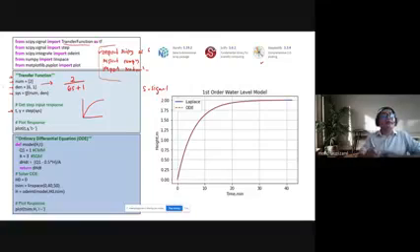After that I will do the plotting. The plotting here I'm using matplotlib. This one is the x axis and y, and these are the features of the plotting. This is just a very basic example of how we can plot the response if you have a transfer function. Another one is ODE.